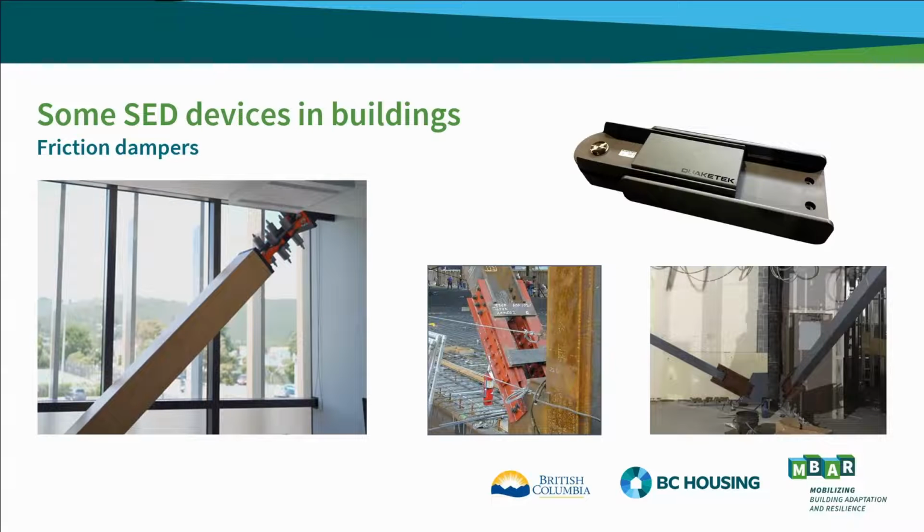Friction dampers. This is similar to the brakes in your car. You know, one piece of material on another piece of metal in friction, dissipating the earthquake's energy. So as these devices are extended and contracted, and metallized plates or specific proprietary material slide past each other, the earthquake's energy is dissipated in heat as these plates slide relative to each other, typically installed in a bracing